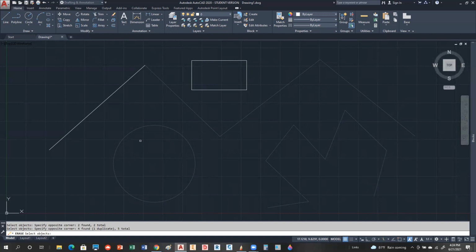So those are called selections of objects. We have the two methods of doing it: noun verb selection, verb noun selection. Again, you have more flexibility with verb noun selection than you do with noun verb, okay? But from my standpoint, I do selections both ways. It just depends on what I'm doing and what I think about. There are, by the way, some of these commands up here that will not let you select multiple objects. So if it says select object, the only thing you can use is a pick box. So there are a few of those that do not allow multiple selection sets.